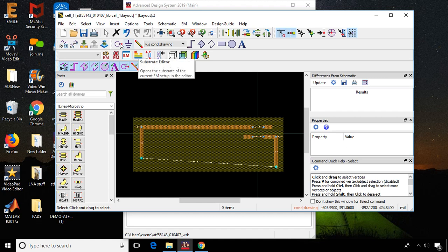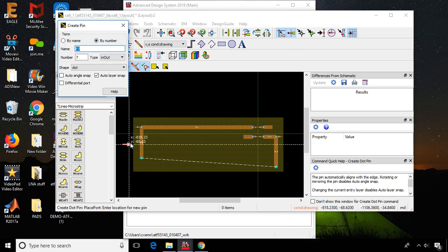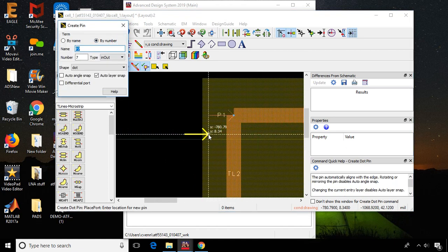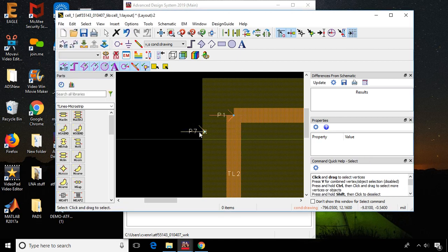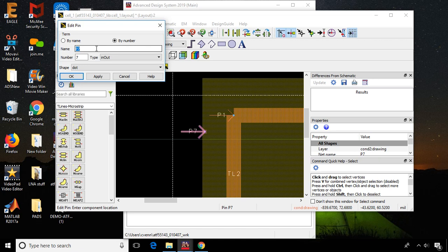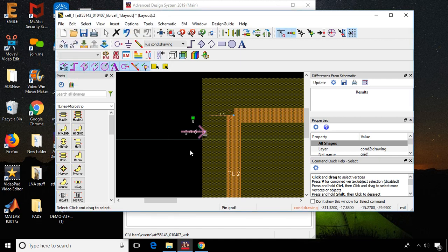But one thing I forgot here actually is we need to specify that the ground plane is a ground. And I've noticed that this is a big deal because it will mess up my simulation if I don't make sure that this is specifically the ground. So there's a code that I put in as GND exclamation point, and then press OK, and this actually creates that this is a ground.